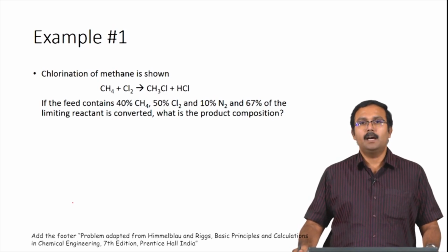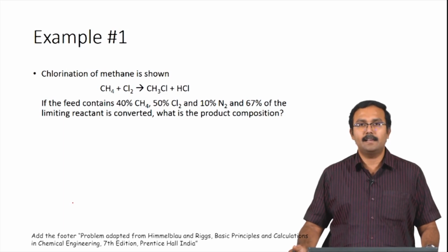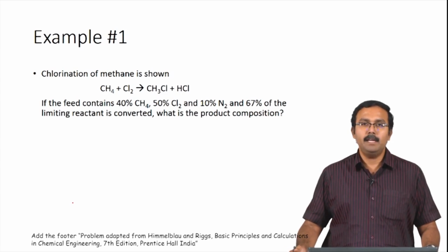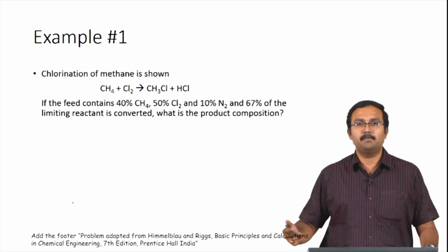If you remember, I had mentioned in one of the earlier lectures that in general mass percentages are used for solids and liquids and mole percentages are used for gases. So, here the composition which is given is for a gas, which would mean the percentages that have been given are mole percentages, and thereby we use 100 moles as the basis instead of using a mass based basis.